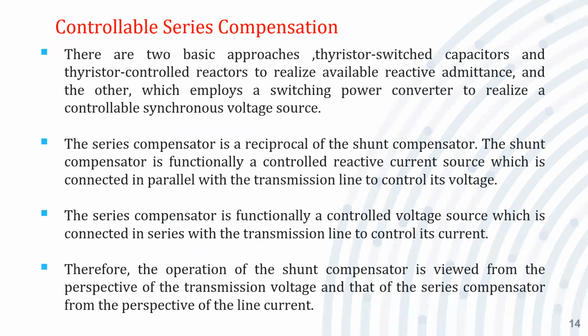Now, in the shunt compensation, we have seen there is controllable VAR generation. We want control over the generation of the reactive power, inductive reactive power or capacitive reactive power. When an inductor is connected, it consumes or absorbs the reactive power, whereas when a capacitor is connected in parallel or in shunt, it generates the reactive power.